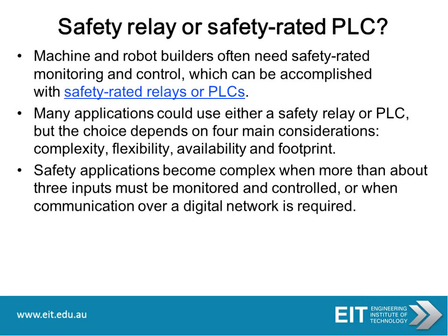Now what we also need to consider is safety relay or safety related PLC. Machine and robot builders often need safety rated monitoring and control, which can be accomplished with safety rated relays or PLCs. So many applications could use either a safety relay or PLC, but the choice will depend on the main considerations: the complexity, the flexibility, the availability, and the footprint.